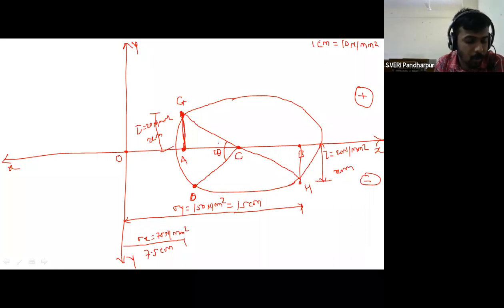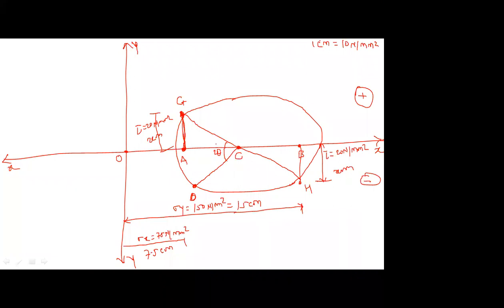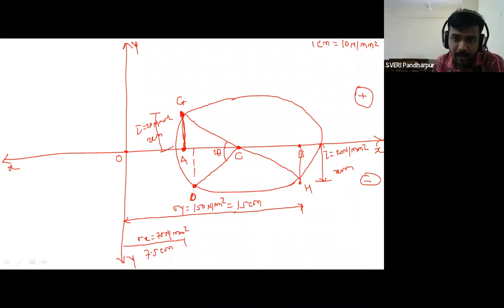Yes, those who are attending online, have you got how the 2 theta angle is represented in anti-clockwise direction? And from point D, there is a dotted vertical line, and you will get one point E. Please keep in mind, while representing the 2 theta, you have to represent in anti-clockwise direction only. And in case number 2, your point A will be the reference point. And in case number 3, which point will be the reference point? Point G will be the reference point.